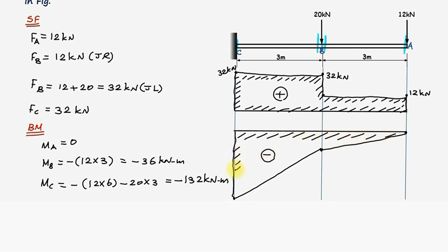So this is how we draw the shear force and bending moment diagrams for the cantilever beam. We start doing the calculation from the free end of the beam.